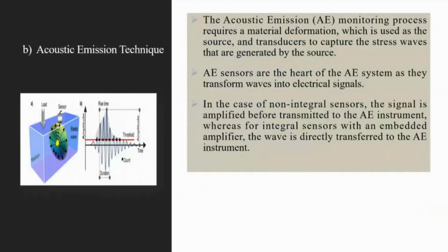Acoustic emission technique. The AE monitoring process requires a material deformation which is used as the source, and transducers to capture the stress waves that are generated by the source. AE sensors are the heart of the AE systems as they transform waves into electrical signals.